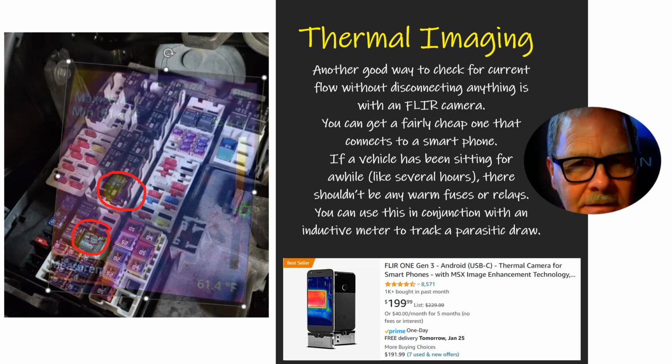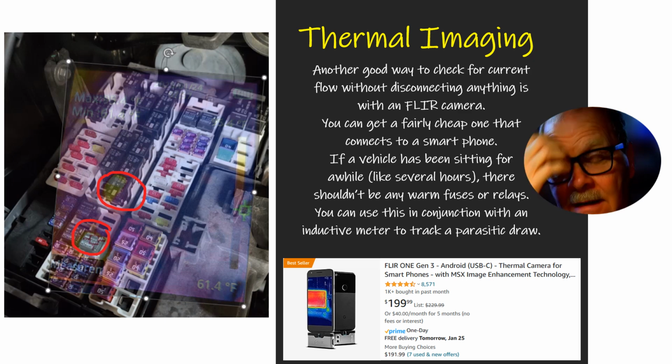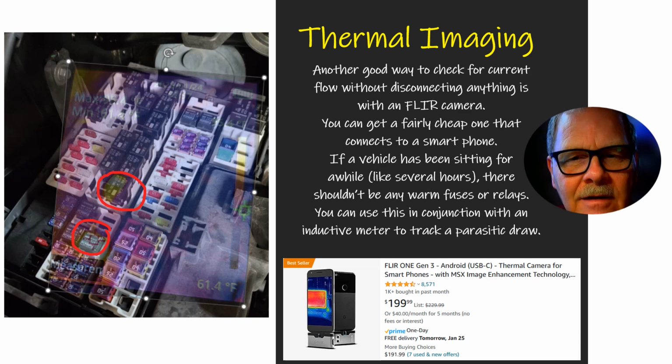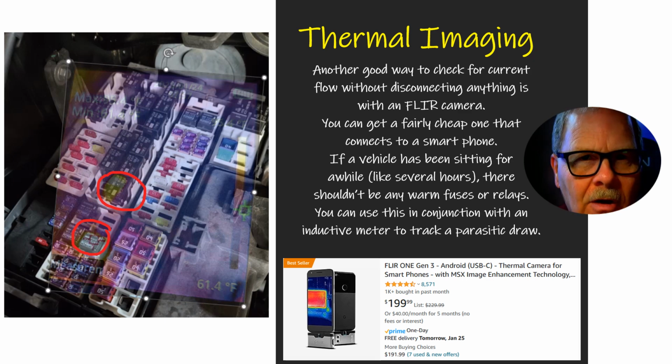Her battery has never been dead from sitting, and we don't drive that truck a lot. It's a 2016 model. It doesn't have a lot of miles on it, and it may sit there a week, sometimes 2 weeks, but we've never once had to jump this vehicle off. However, it's got just a little whisper of current going through these two relays. So just because you've seen a warm relay with your forward-looking infrared camera, doesn't mean there's a problem there. You see what I mean? Because this truck hadn't been started since Sunday when we drove it to church.